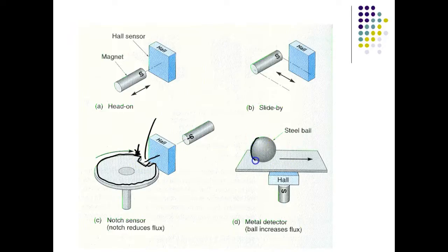Here we're sensing metal balls, so this is a steel ball, which is magnetic. Here we're using the same situation where I have a permanent magnet sandwiched between the permanent magnet and what we're trying to sense, which is a Hall effect sensor. So when the ball moves across there, it concentrates the magnetic field through the Hall effect sensor, and we can use this right here. We can literally get pistons now, hydraulic or pneumatic pistons that we use to move things.